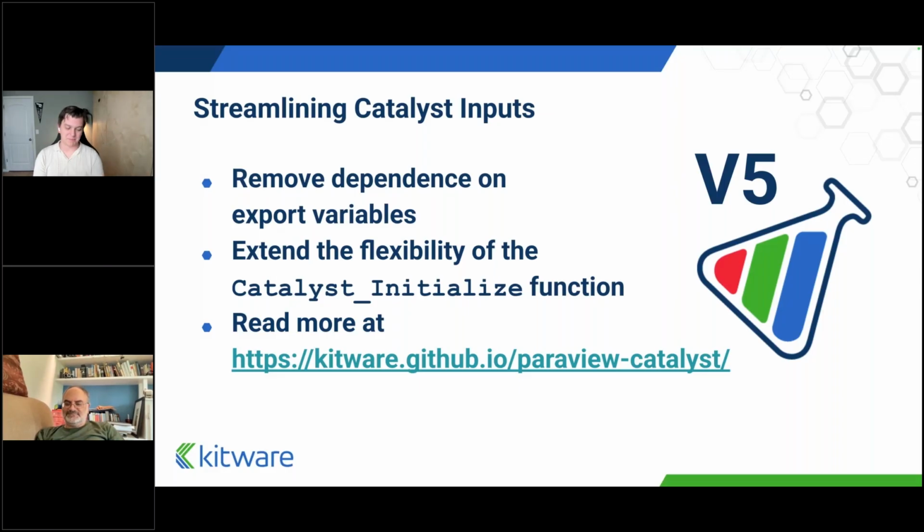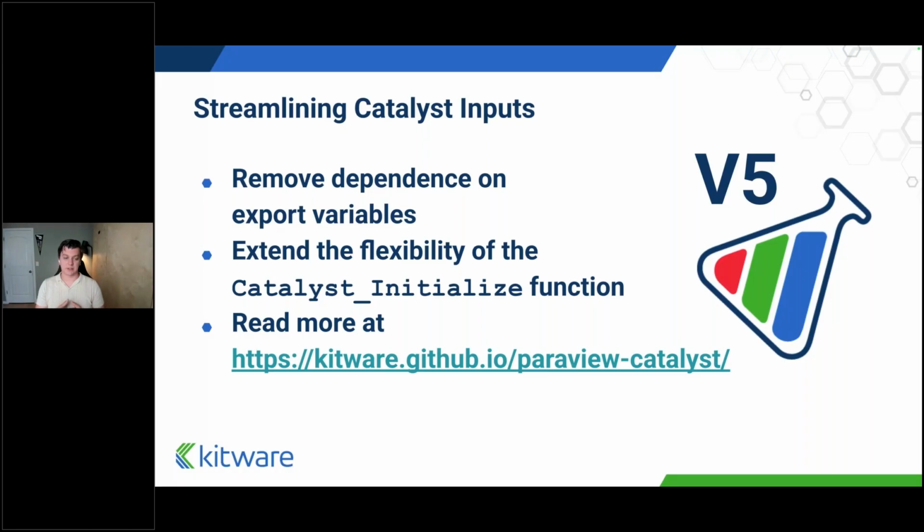So one of the fantastic capabilities that Catalyst brings to the table is that it is built for MPI-based simulation parallelization from the ground up. If you have a simulation domain decomposed onto multiple MPI ranks, and you run this exact code on each rank's data, it will be passed through Catalyst, and ParaView on the back end will interpret that correctly and will produce a partitioned data set that represents your data faithfully.